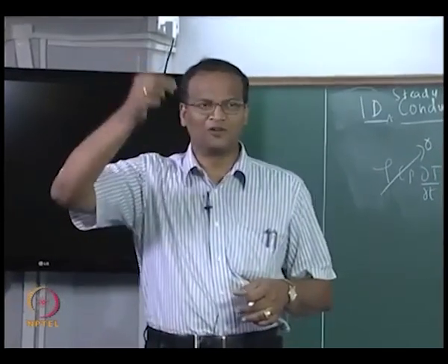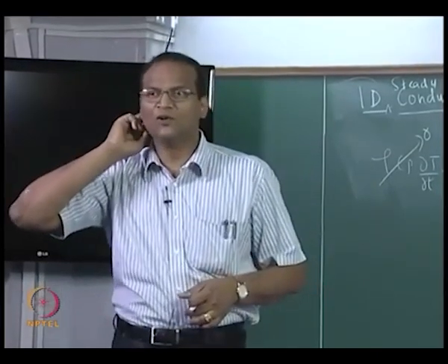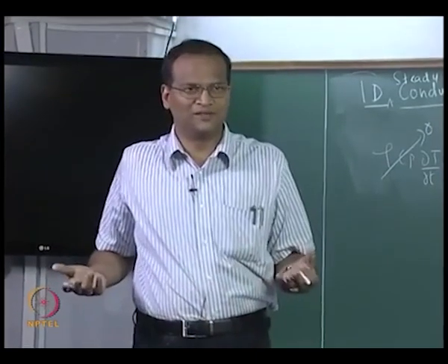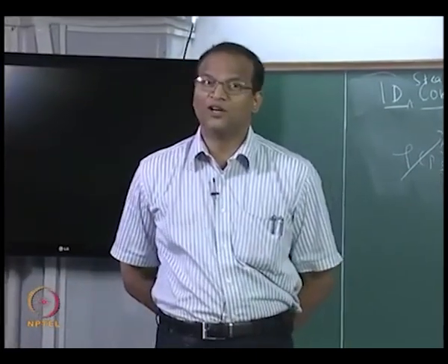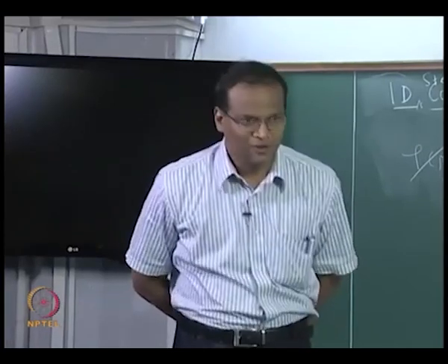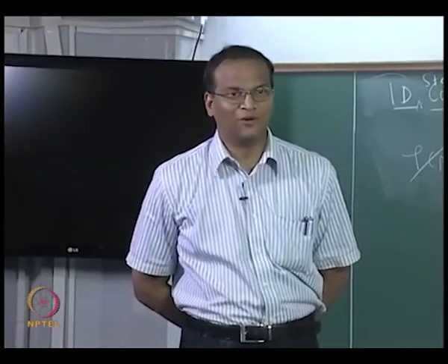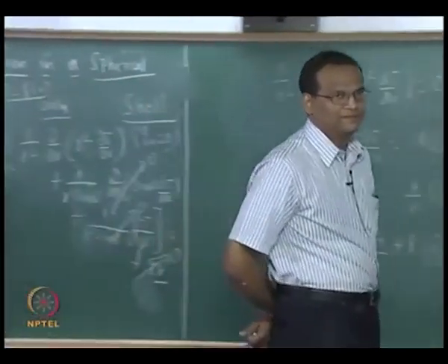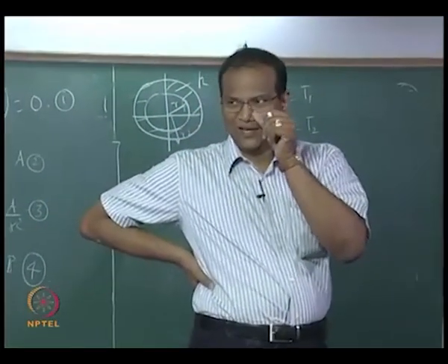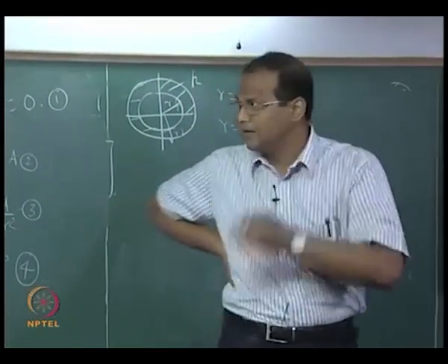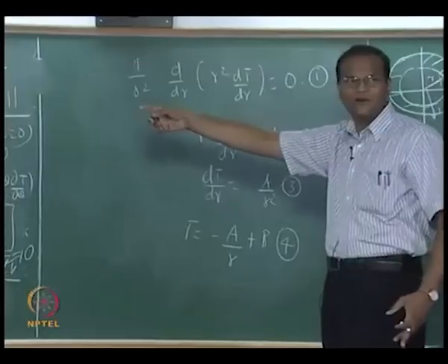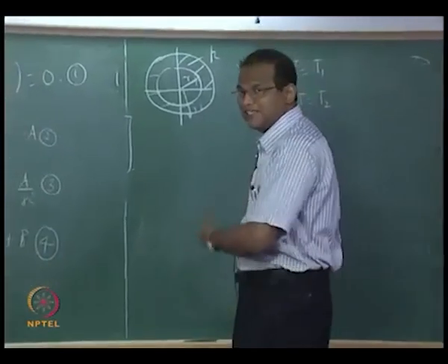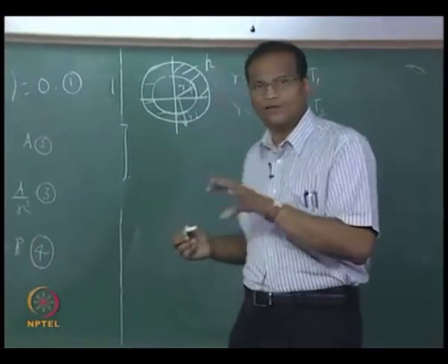So then you need a vent and slowly the oxygen, some liquid, will be lost. So you will have to find out, suppose this journey takes so many hours, at the end of the day how much liquid oxygen will be lost. So you turn around and say, let us say 2 kg per day alone is allowed. If 2 kg per day is to be allowed, what should be the thickness of the insulation? That is engineering. Okay. So this is a very practical problem, right? What we started out with very innocuously with some mathematics, we can apply to some hardcore engineering problem, right? So I will give you the example now. We will take liquid oxygen and a spherical tank and do that.